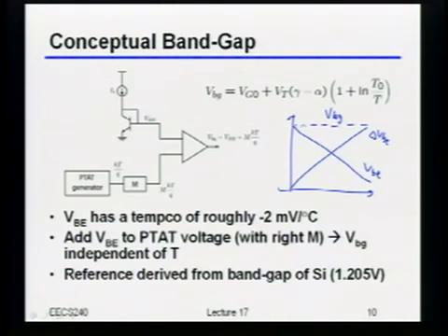Okay? What if the silicon changes temperature? Ah, indeed it does. So are band gap voltages really constant? No, they're not. They actually do shift a little bit. Now, there's all kinds of tricks people have come up with, so-called curvature correction and so on, that basically try and counter that. But none of them are perfect. Because again, there has to be some fundamental physical thing that you can rely on to say, okay, I'm pinned to that thing.